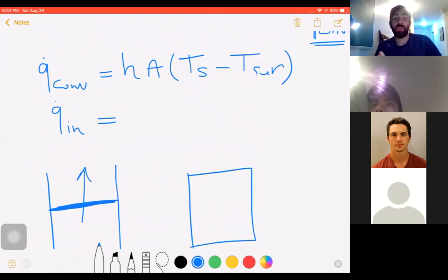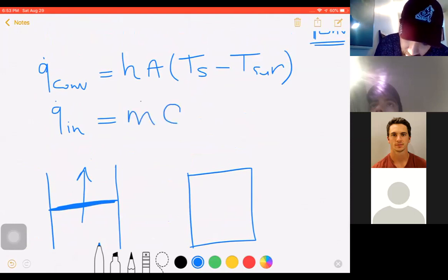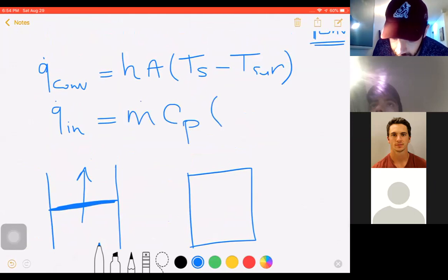It is really important to know where we have to use Cp and where we need Cv. So since my problem is a constant pressure problem, I will use Cp, and the temperature difference is T2 minus T1.